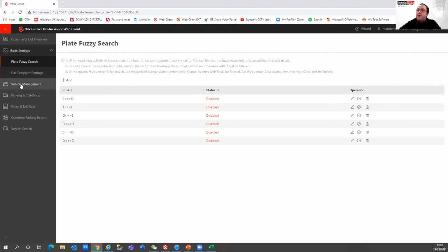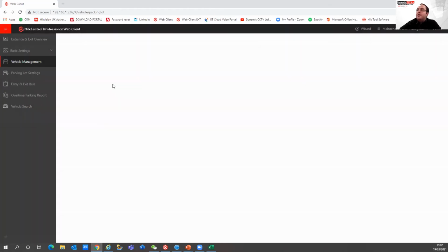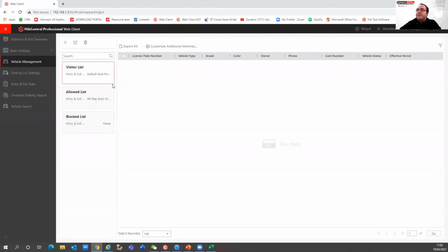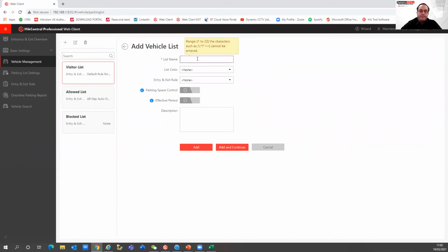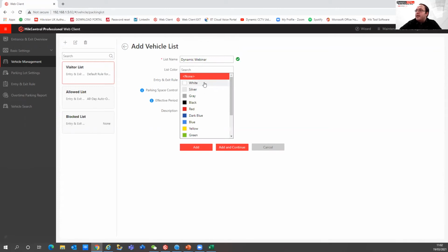If we go into our vehicle management section, this is where we can set up our different plate lists within the HikCentral platform itself. You can see we've got a visitor list, an allowed list, and a block list already set up. To create a new list, we can click on add at the top. I'm just going to call this dynamic webinar. I can set a color for the plate list, so I'm just going to give it green.